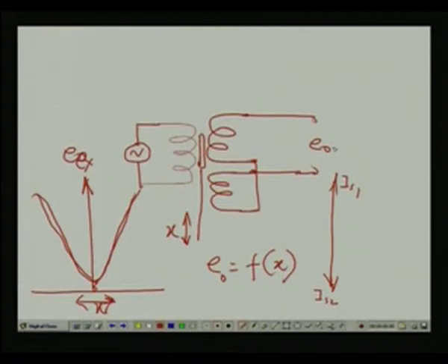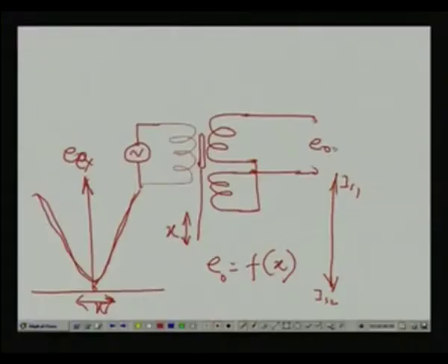Now, all these things you will find: the null voltage cancellation, and whenever you are using an LVDT, I need a separate excitation voltage, because that is like a bridge. As you know, we use a Wheatstone bridge. A Wheatstone bridge also needs an excitation, either DC or AC, it does not matter, but in the case of LVDT, since we are using a transformer, there is always an excitation. This can be easily avoided if I use a particular chip available, right. Inherently you can vary the frequency of excitation, and I get an output voltage which is free from all these problems.